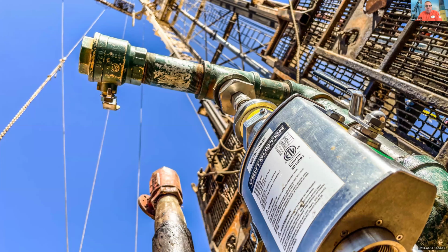In this particular shot that you see here, this is where we were actually measuring on an orphan well as the rig was getting stood up around it. We wanted to make sure that we got a good 12-hour test prior to that. The key here is that if you look at that certification in the center of the photograph from Intertech, that is a Zone 0 certification, or Class 1 Division 1 certification.